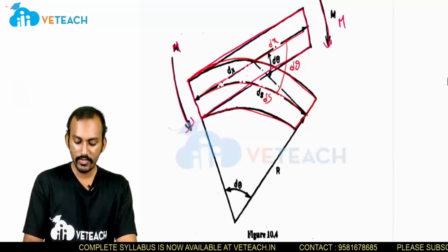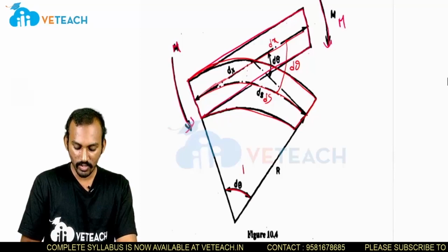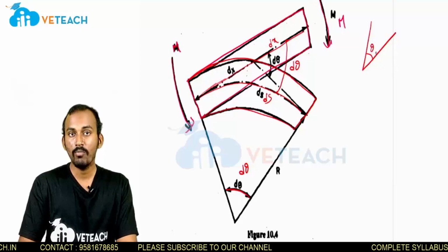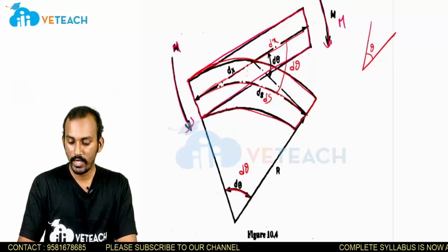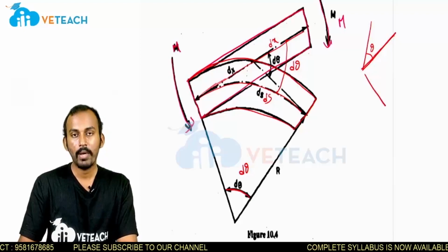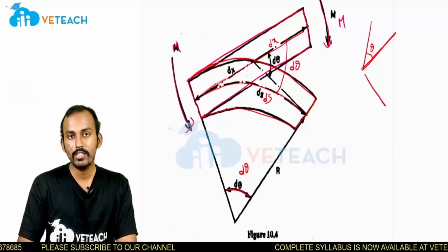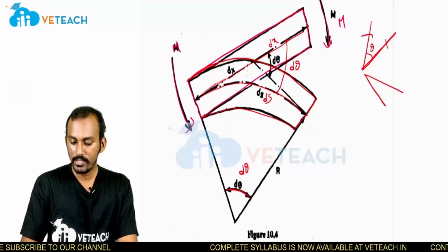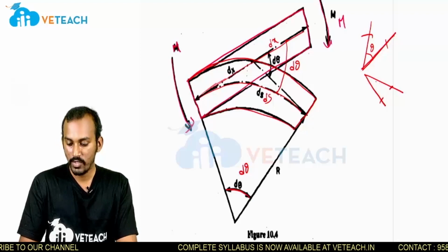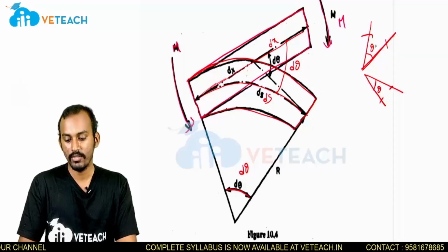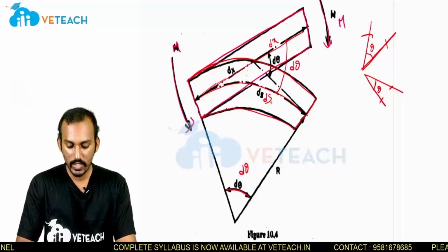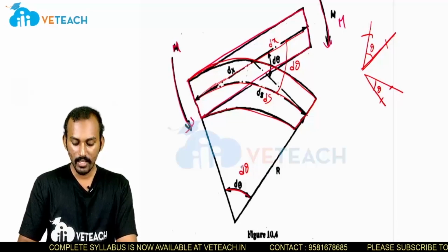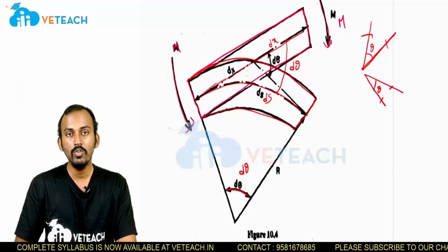So here if you see, if this angle is theta, then this angle is also equal to d theta. Okay, why? We have two forces with an angle theta. Now I am drawing the perpendicular for these two forces. For example, for this force I am drawing a perpendicular. Okay, so similarly for this force also I am drawing a perpendicular. Okay, so these two members are exactly perpendiculars. So then the angle between them will not change. If this is theta, this is also theta. Okay, so here also we are applying the same condition. These two lines are the perpendiculars. So that is why this is also equal to d theta.